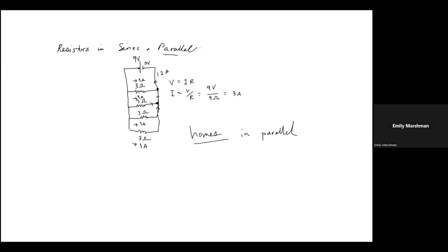Because we said as these connecting wires get more and more current, they're going to get hotter and hotter and hotter until eventually they could get too hot and melt, right? So that's why you have a circuit breaker that shuts off at a certain amount of amps.